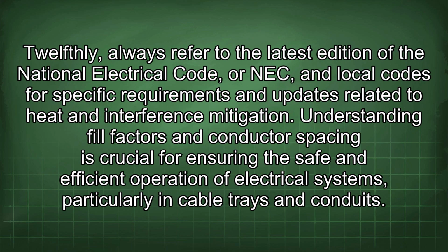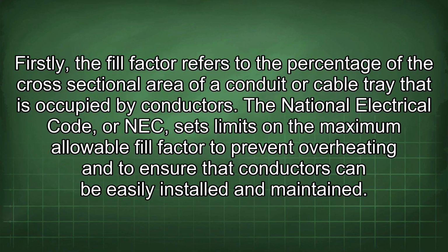12thly, always refer to the latest edition of the National Electrical Code, or NEC, and local codes for specific requirements and updates related to heat and interference mitigation. Understanding fill factors and conductor spacing is crucial for ensuring the safe and efficient operation of electrical systems, particularly in cable trays and conduits. Firstly, the fill factor refers to the percentage of the cross-sectional area of a conduit or